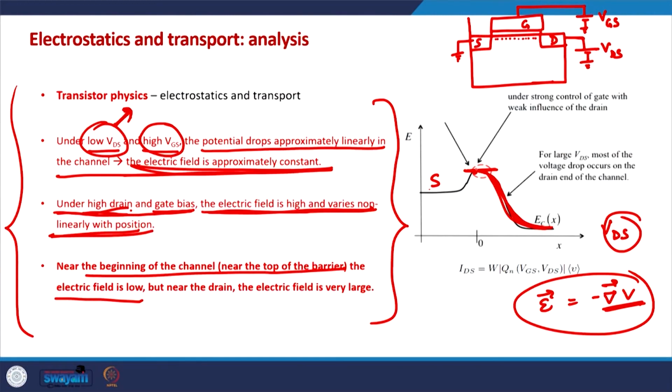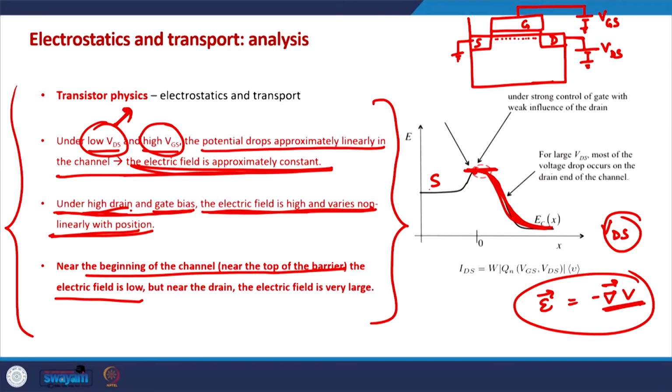The electric field at the top of the barrier is 0. It means that just at the top of the barrier the electric force is also insignificant, it is almost 0, and in most cases the thermal velocity of the electrons plays an extremely important role here, because the velocity due to the force is not there, it is just the thermal velocity with which these electrons enter.